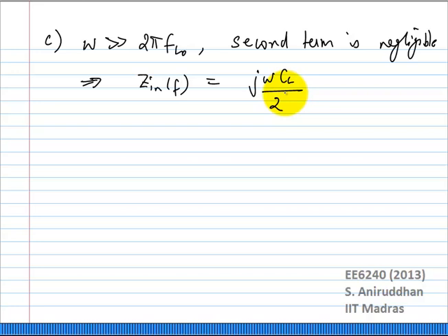If you want to convert this to a single balance mixer, you will have to divide this by half. If your switch is non-ideal and has a switch resistance, you will have to add the switch resistance and then divide it by half.